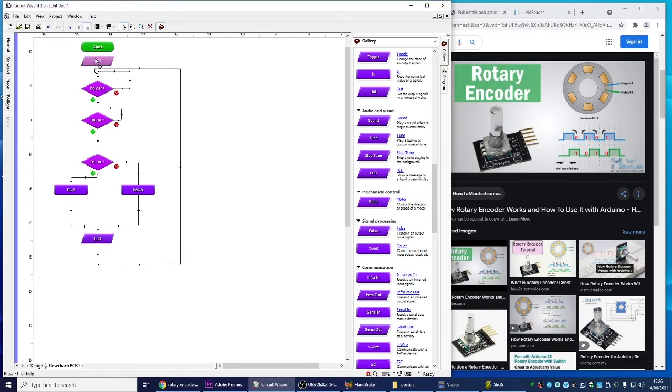So we want to make sure this is at the beginning, and then as soon as you turn the dial, we'll get a change in the value. But basically, it'll only refresh the LCD when it's gone through a whole loop. So basically, let's look at the scenario. So we're looking for nothing's going to happen until this is in the off state. So it's either in this state or this state. And then we're looking for a rising edge. So let's say we're going this way, and we're looking for that point where it goes from off to on.